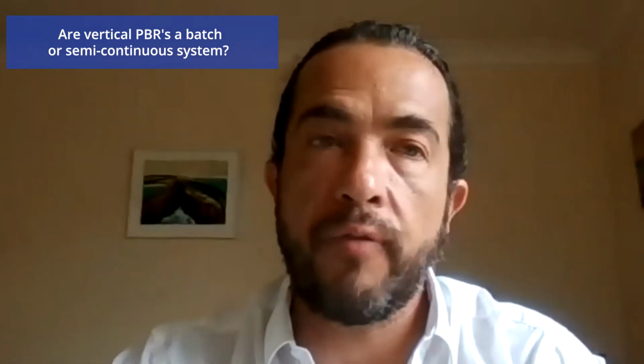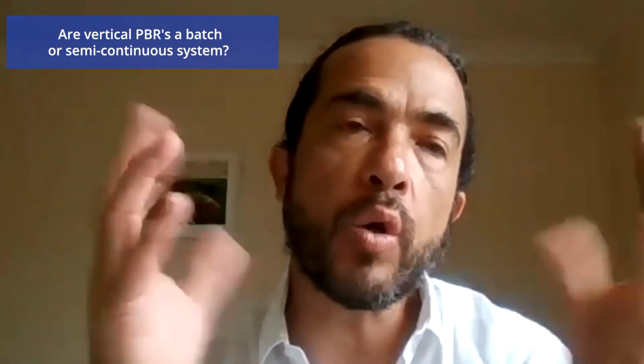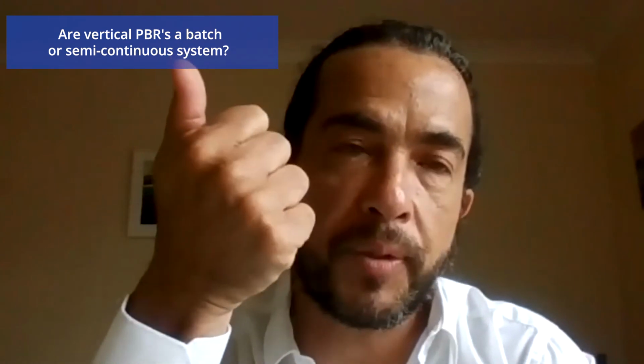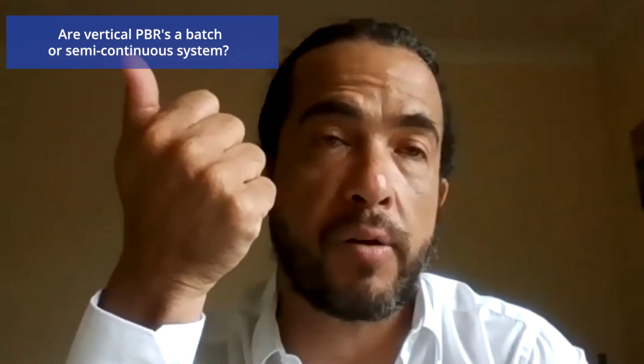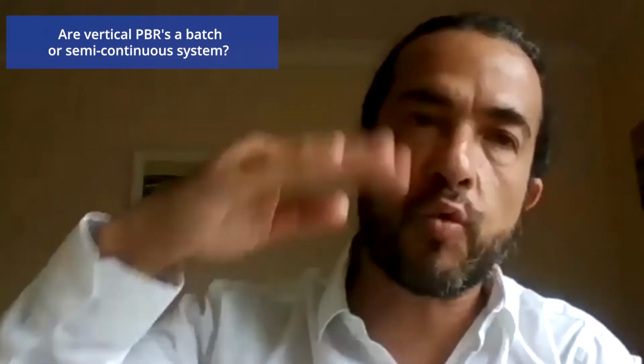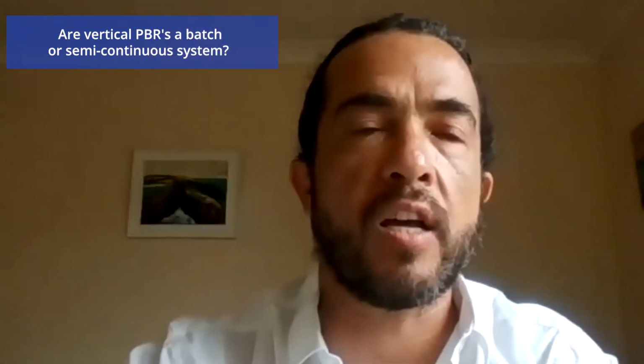Super. Okay. I have some questions. So, Claudio, are the vertical PBRs a batch or semi-continuous system? It's a semi-continuous system. You can run in batch mode if you want, but normally it's semi-continuous, because the whole idea is to run the reactor first to take up the ammonia and phosphate. So we do the environmental service by bioremediation. The idea was to run on a semi-continuous basis. That is why we were able to take up a lot of ammonia and phosphate.